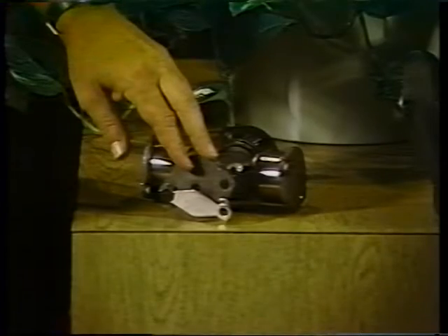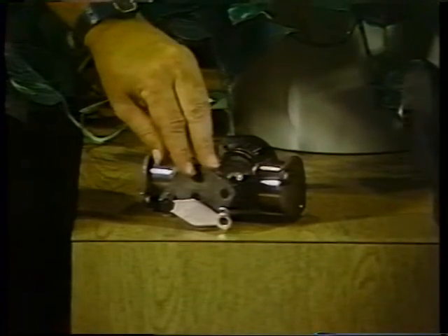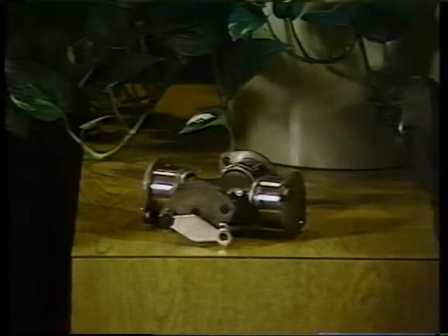Okay, I understand all that. Is there anything else we need to cover? Oh, just one more thing. Over-torquing the retaining straps or bolts of the drive shaft. Now, this means you need to properly torque the U-joint bolts to Spicer recommendations when installing a U-joint kit. Under or over-torquing bolts can lead to early cross failure.